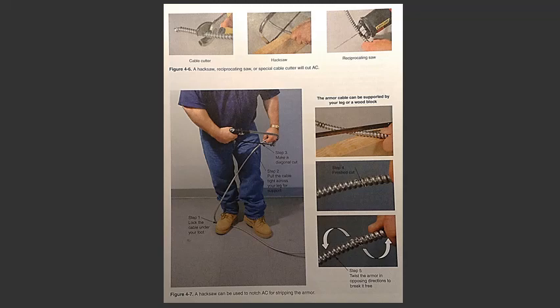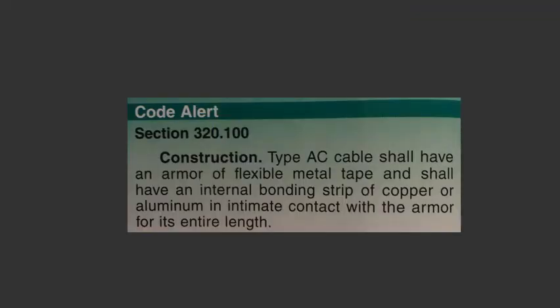Once the armor is cut through, it can be twisted off the inside wires. The aviation tin snips. The first step is to bend the cable sharply where the armor will be cut. This will cause the interlocked armor to disengage. Twist the armor to force it to expand and expose the twist in the armor.